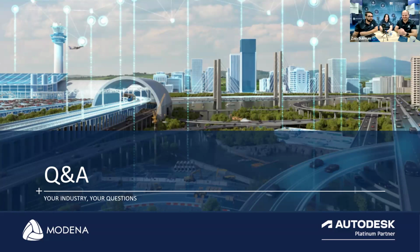Okay. The next question, can you use different versions of the software, for example, Revit 2022 and Robot 2025? No, what's important to remember is if you are going to be using all three software, you would basically want to be using the same version. So if I'm using Revit 2024, my Advanced Steel should be 2024 and my Robot Structural Analysis should be 2024. You don't want to basically mix and match. It will lead to inconsistencies and a lot of the times the models won't open in your other software.